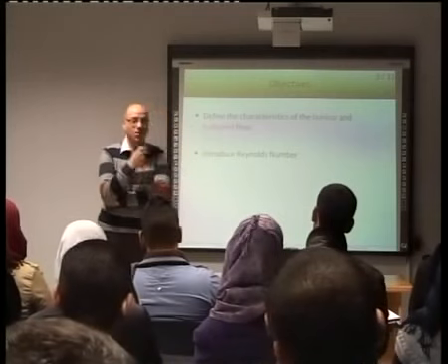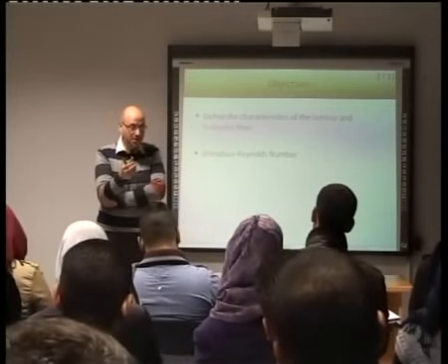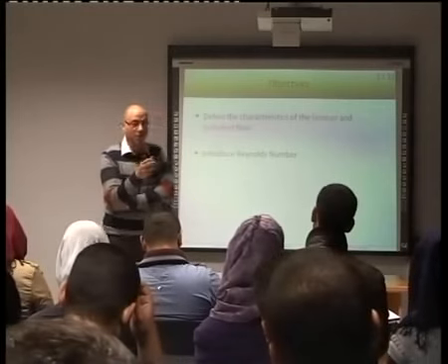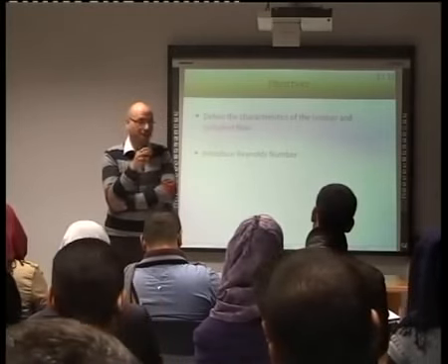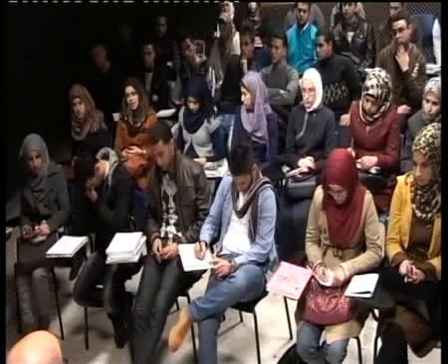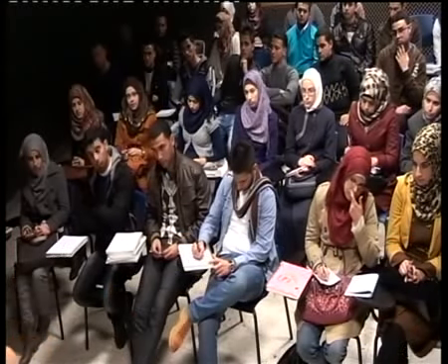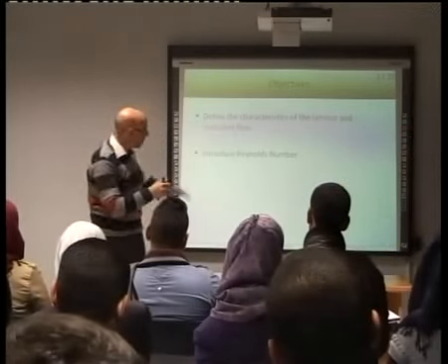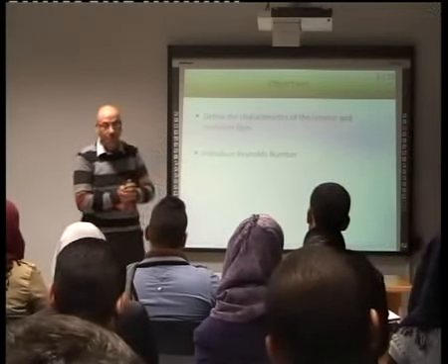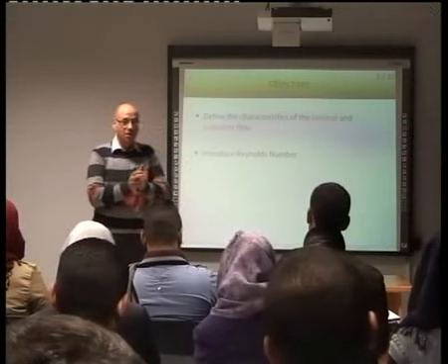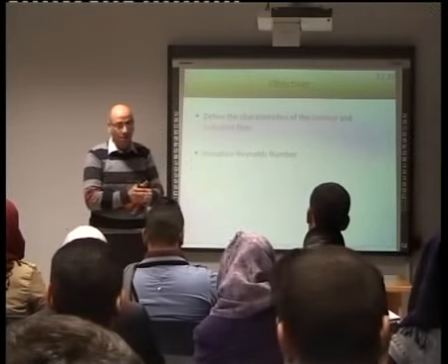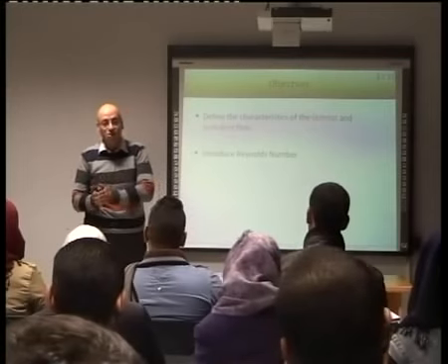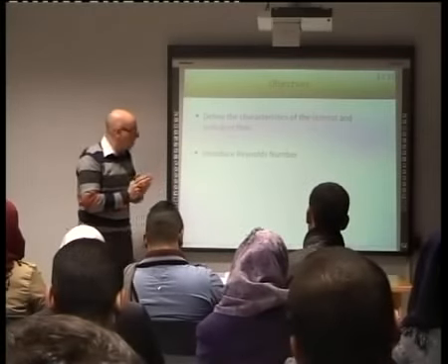Flow type, when we say, for example, steady, or when we say uniform. What is meant, by the way, by uniform flow? Can anybody answer? Yes, please. No change with place or location, with distance. So I would assume that the velocity will not really change from location to location. This is uniform flow. And when we say unsteady or steady or transient, what does that mean? Yeah, there's no change with time, then that would be a steady flow.